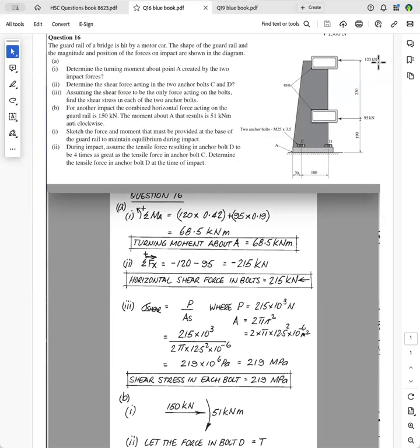Remember, not very many people know the magnitude of 120 kilonewtons. When you're dealing with kilonewtons, all you have to do is move the decimal point one place to the left, and that will tell you how many tons it is. And you know what a 12-ton truck looks like, so you can immediately relate that force to something you're aware of.